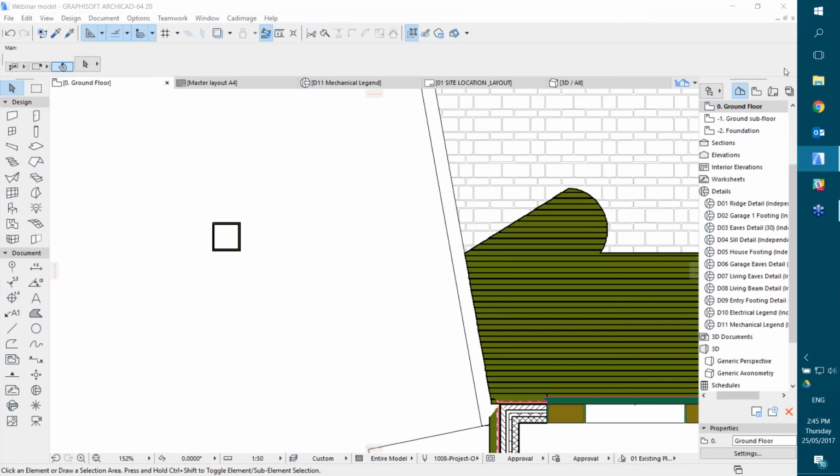Okay, we've got some questions here about the roof covering, mostly by the look of it. Is it possible to put more than 2 downpipes? Actually, I forgot to show you the downpipes, didn't I? If we pop back into 3D, we can have a look at those quickly. If I just select my roof covering here, it doesn't put downpipes on by default because it doesn't really know where they should go. It wants you to tell it.